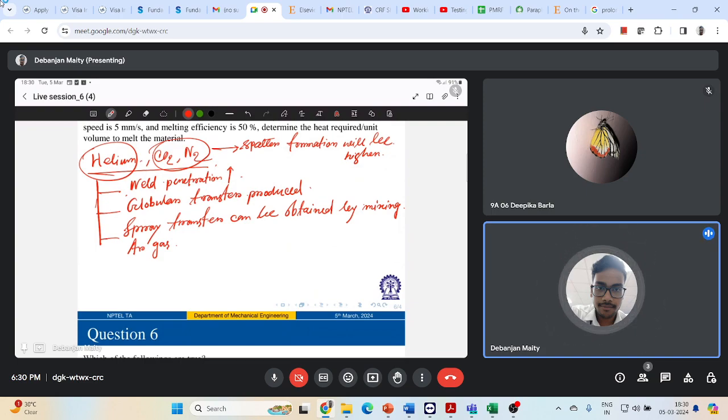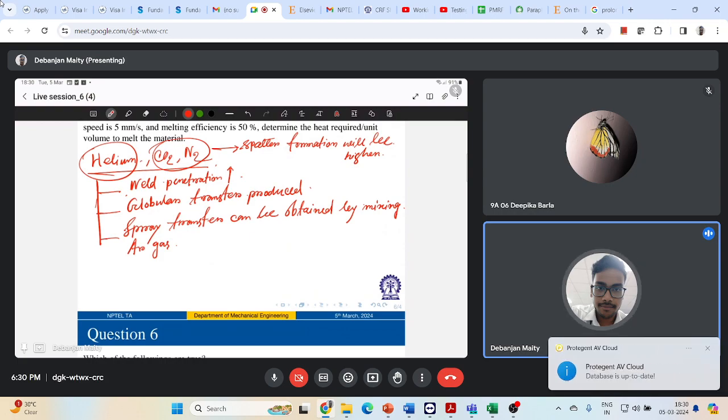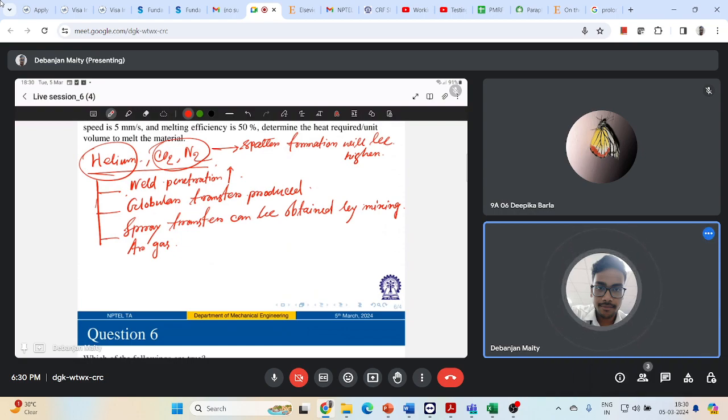Now there are some applications of these gases as a shielding medium. Mainly carbon dioxide should be used if you are using mild steel as your object. So carbon dioxide can be used to shield arcs in mild steel. Nitrogen is also useful; it can be used mixed with argon to shield aluminum alloys. So you always have some particular application when you should go for these active gases.